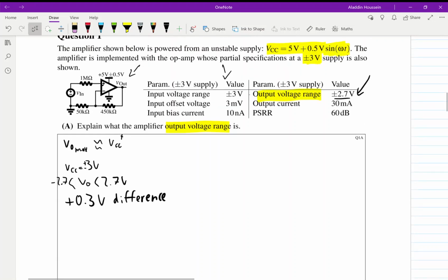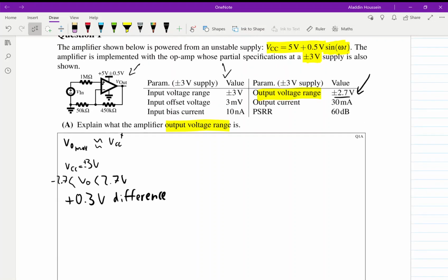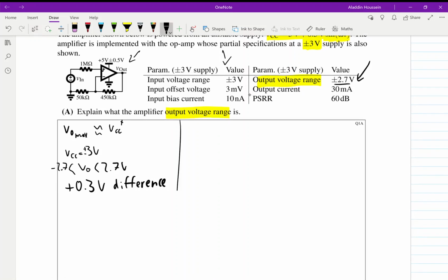And we want to take the worst cases at all time because we want to assume the worst possible thing has happened and account for that. Now, what we see is that this will range from 0 right up until 5.5 volts or 4.5 volts. Yes, small ranges tend to be bad, so we want to pick the smallest range possible, right? And in that case, it's going to be 0 to 4.5 volts.